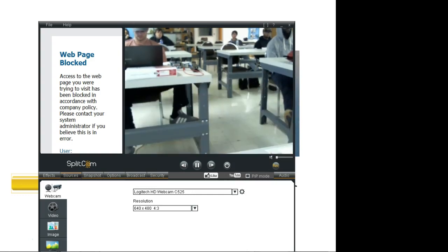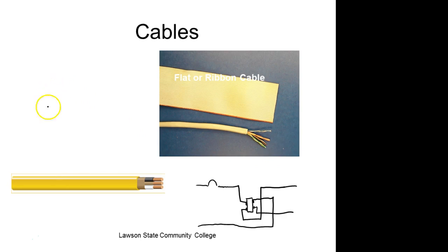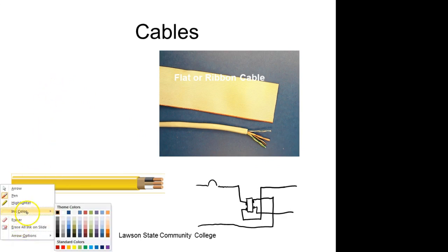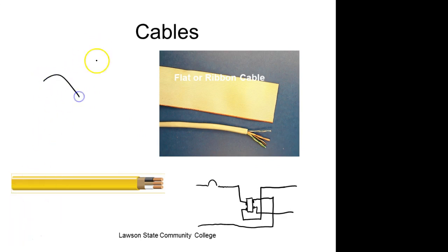Now, good electricians will come up here and they'll bring their black wire in, and then they'll twist it together. They'll have what they'll call a pigtail and twist it together. I should be doing it like this. And then they'll send it out, and then they'll put a wire nut across this thing. I don't know what a wire nut is. And in that way, if a plug goes out, it's not going to kill any plugs down below that. This is the way good electricians wire them. But most of them don't do that because it takes time.